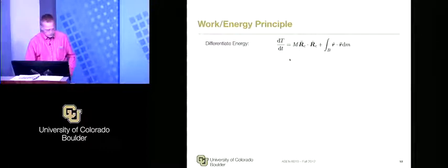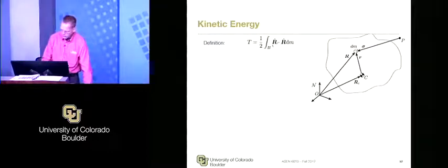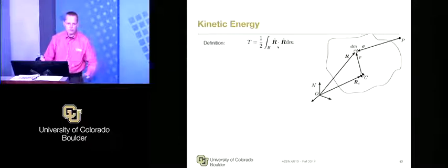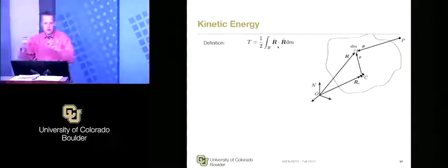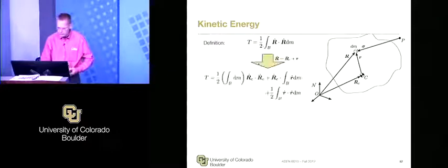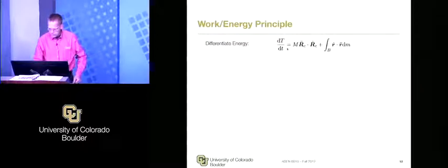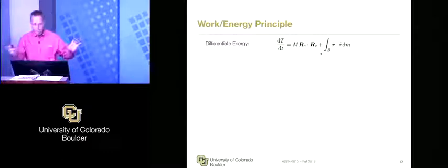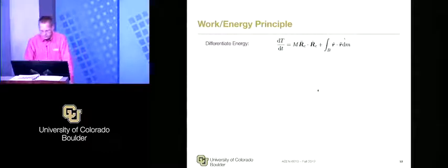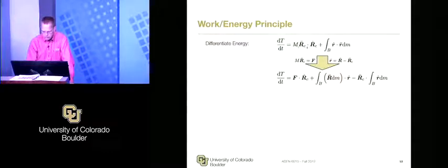If you go back, this one with the chain rule, I'm going to get r double dot dotted with r plus r dotted with r double dot. Again, dot products commute. So it's 2 times r double dot dotted with r, and the halves cancel out. So you end up with this, plus the same thing with the other part, right? We've broken it up into 2 sections. And now we can start to substitute things. Mass times the inertial acceleration of the center of mass is the total force acting on the system, the total external force, if we want to be more specific.